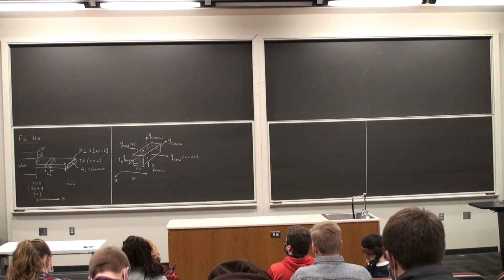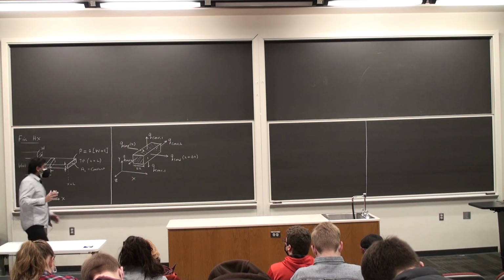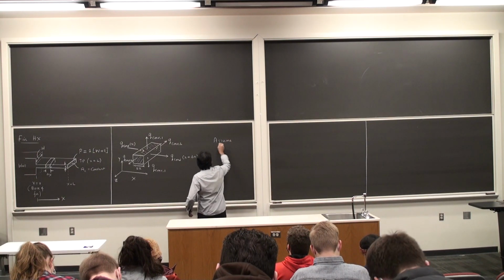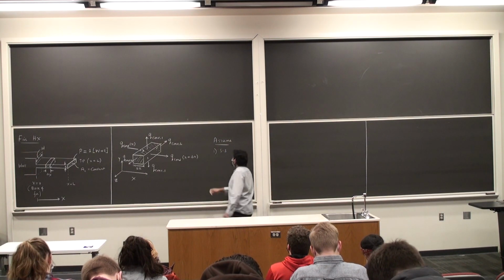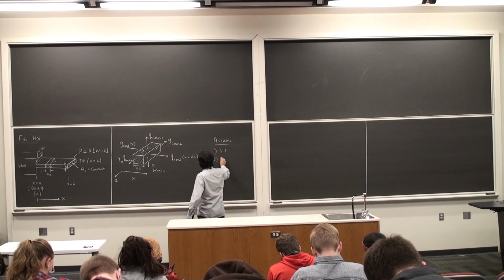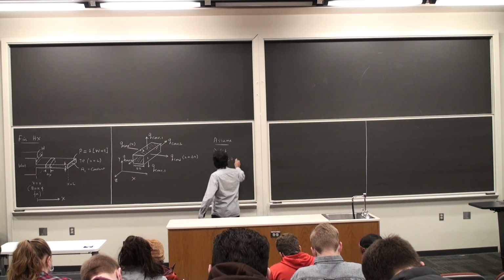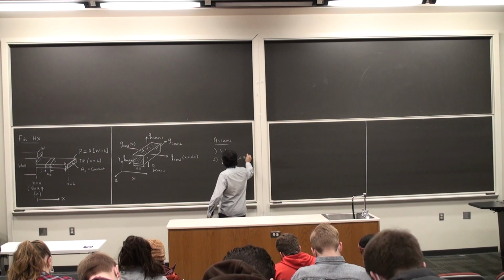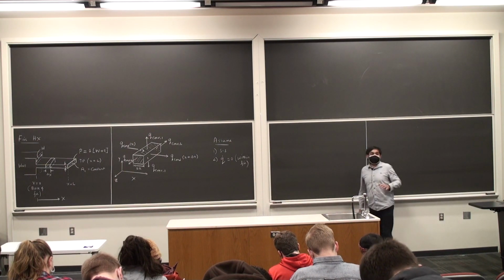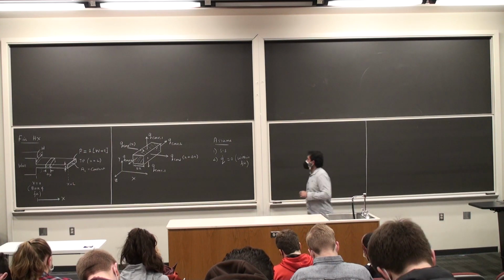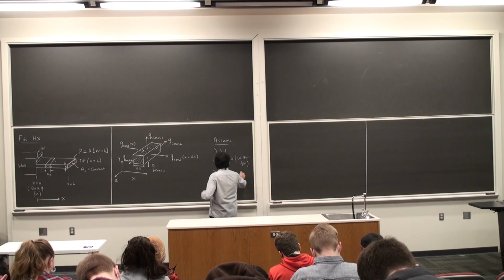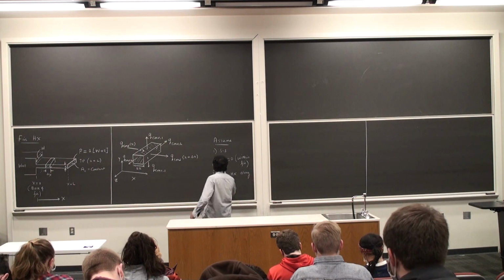Alright, and then a basic energy balance, or writing the first law. There is no heat generation within the fin, so my assumptions: steady state, so no time changes coming into play. Then no heat generation within the fin, Q dot is equal to 0. Within the fin, it does not necessarily say that the heat generation within the wall is 0, it's just within the fin, okay. Then one-dimensional heat transfer along the length of the fin.